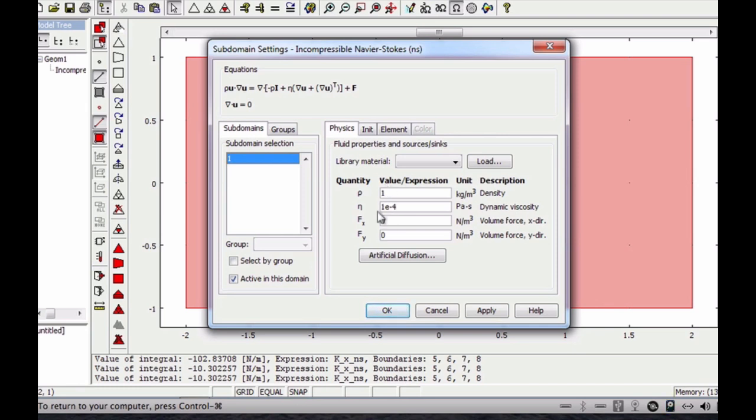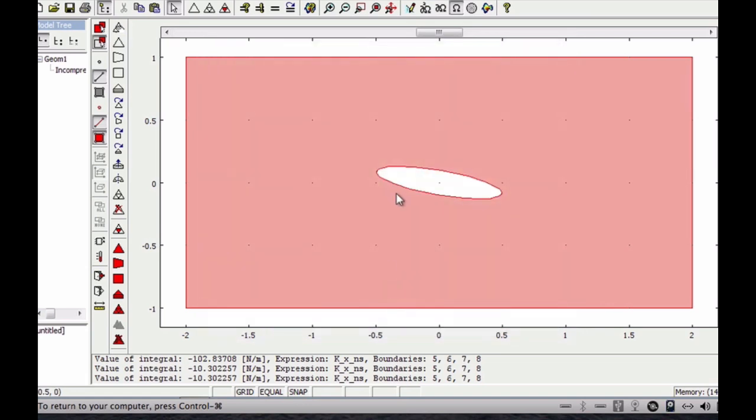We have a viscosity, so this is what we called mu before, the dynamic viscosity. And we choose a whole bunch of different viscosities. I think we changed them between 100 and 10 to the minus 3. I stopped at 10 to the minus 3 because it crashes after that, because 10 to the minus 3 is a very big Reynolds number, and it doesn't work very well at the largest Reynolds numbers. So what we can do is run it and solve for the system.